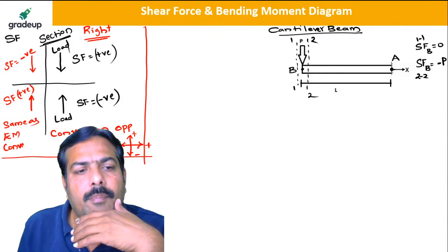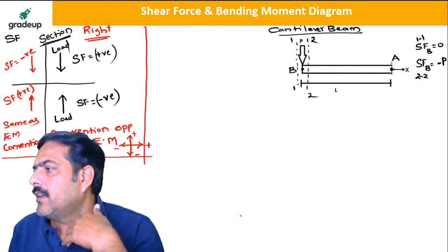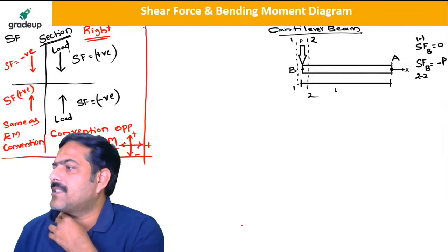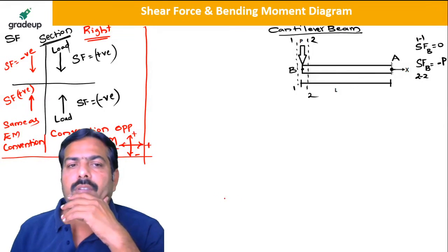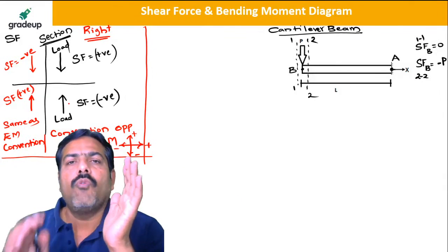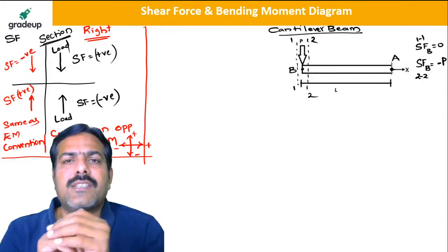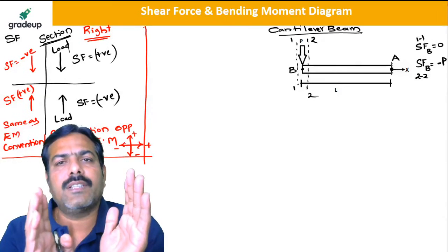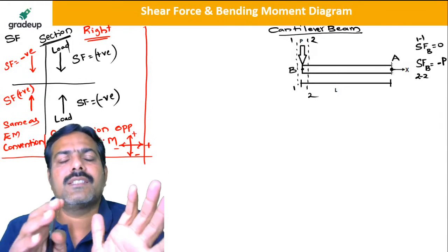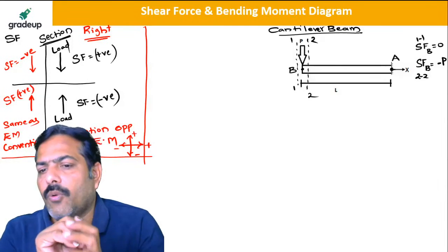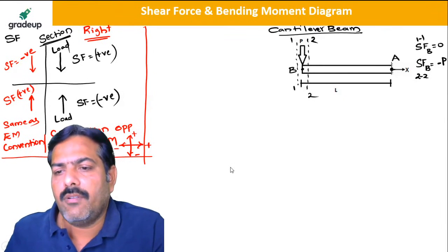So my dear friend, please keep in mind that whenever you solve the section on the right side, whatever is given, the opposite of that is the shear force, and when you are solving the section on the left side, whatever is given is the shear force. Is it clear now? Whatever is given is the shear force.